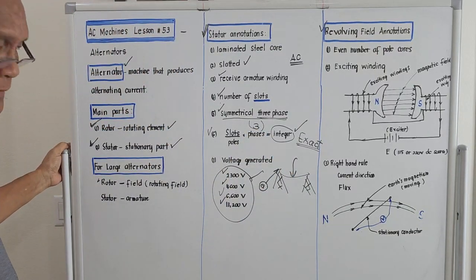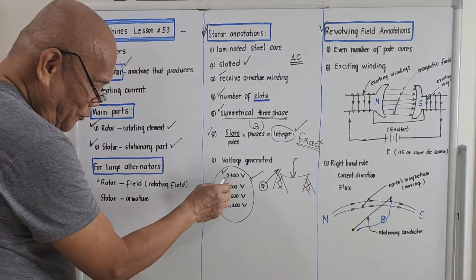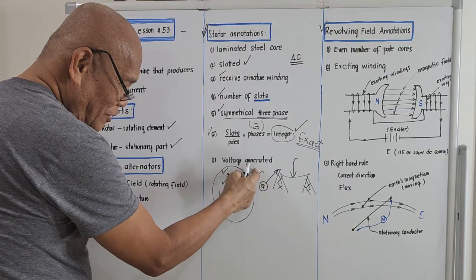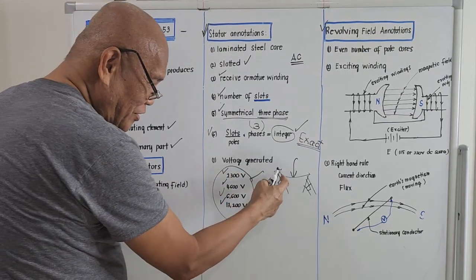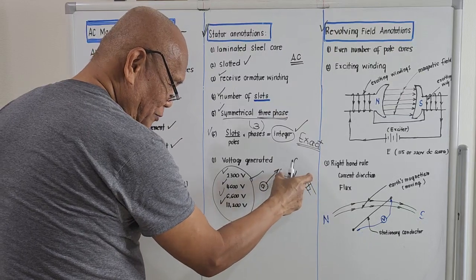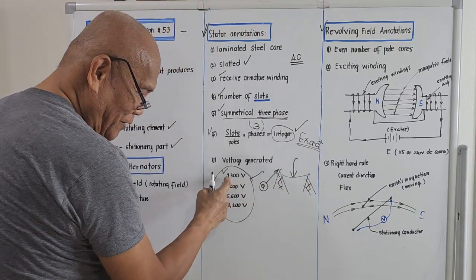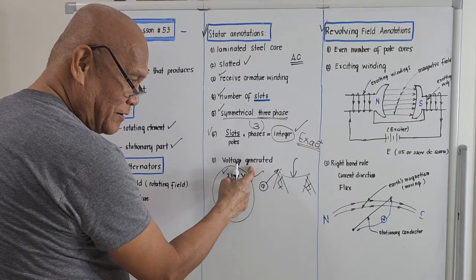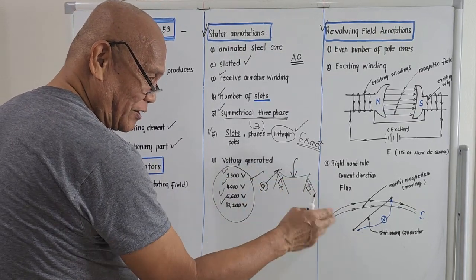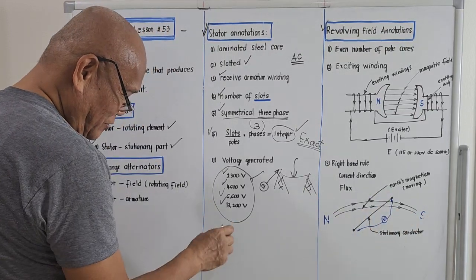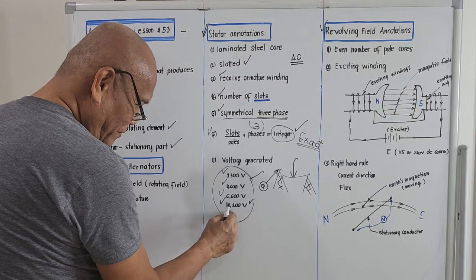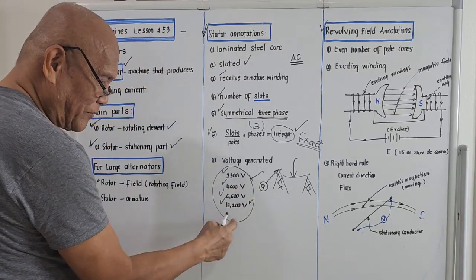If we feed 2,300 here, it's not so much, because this transmission line is actually very low. If this transmission line is 500 miles and you feed only 2,300, before it reaches 500 miles, maybe the voltage is too low already. So it's possible that we will be using 13,200 maybe. But this 13,200 is still very small.